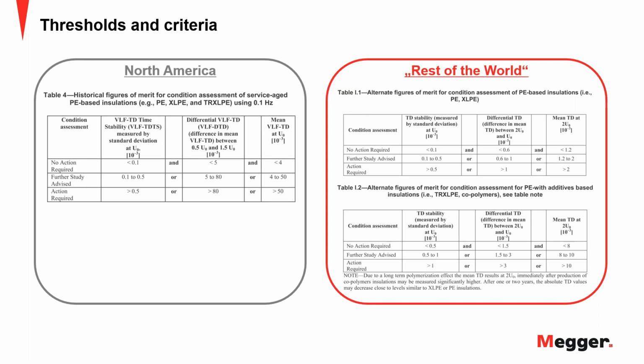The liquid-filled can typically take much more PD because they're oil-filled for the most part. They can take much more because the oil is snuffing out the PD, compared to the solid dielectric. Anything that's solid dielectric that has PD has a void. The void doesn't get any better. There's nothing to snuff out that PD.